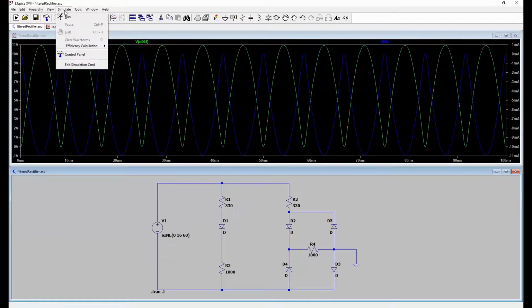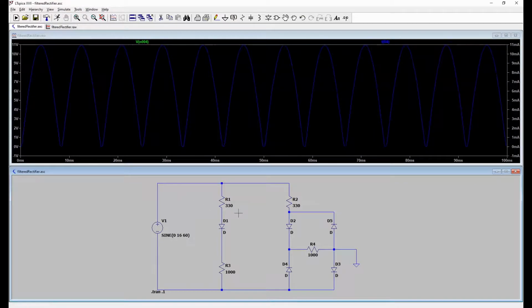So now, when we do the simulation, if I click on this point, it'll give us a positive voltage, and if I click on this, then it will show us the current polarity relative to that direction. And ideally, with this being positive and this being less positive, the current is flowing left to right, and when we click on that, we not only get a positive voltage, but a positive current. At the moment, you can't see the current because the scaling is exactly the same.